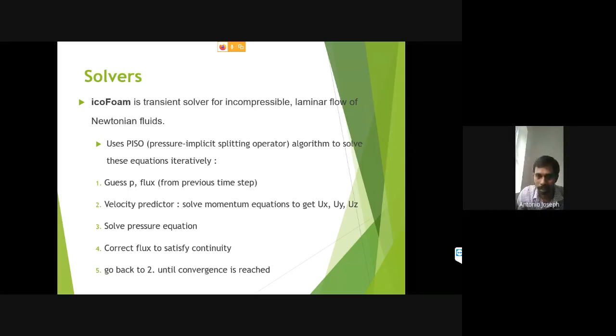Hari Krishna, you are right. The grid independence depends on the mesh quality, so we need to adopt the same methodology for creating the mesh. In the case of snappyHexMesh, it doesn't matter because we are already giving the quality of the mesh that is expected, and that's why it's showing some iterations. We can see some iterations happening while we are executing the snappyHexMesh command.